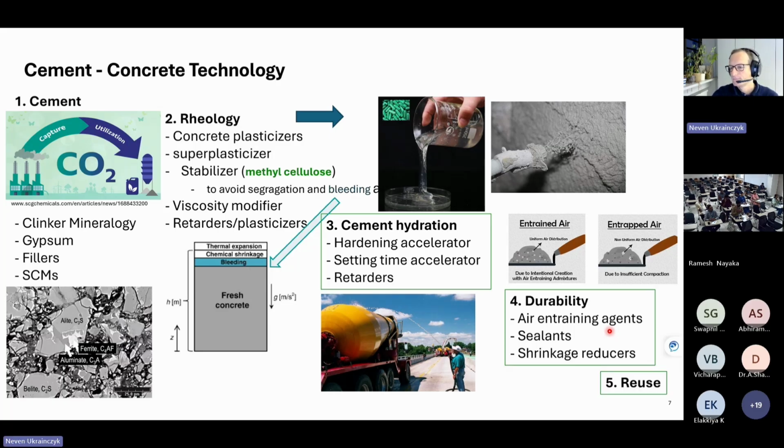And in the end, here maybe just to say we also have the entrained air, which actually helps durability because those are very small air bubbles that are very nicely distributed, and they also help rheology but also help durability because those are closed pores and very nicely distributed, especially for freeze-thaw, for example. If you have freezing like in Germany, now it's around 0 temperature, of course you need some very finely distributed small volume where the ice can grow its crystals.